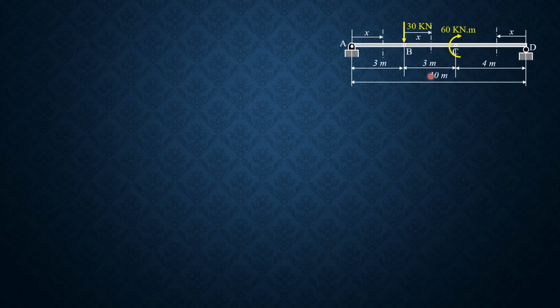Then for the slope at C, we apply a couple at C. So just concentrate on the couple. The reaction here due to the couple C, summation of moment, times 10 equals the couple. Therefore, the reaction here is couple over 10 or 0.1 C. Since due to the actual loads it was 15 upward, then due to the couple, 0.1 of couple. So this is now 15 plus 0.1 of couple. Likewise, summation of vertical forces, this should be 15 minus 0.1 of C, or the couple.